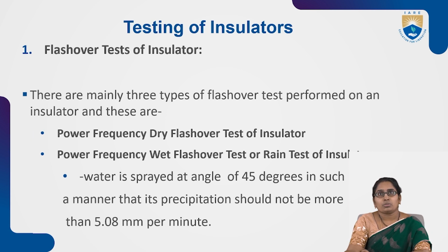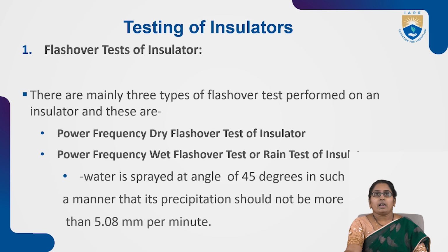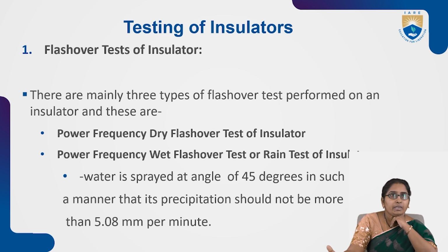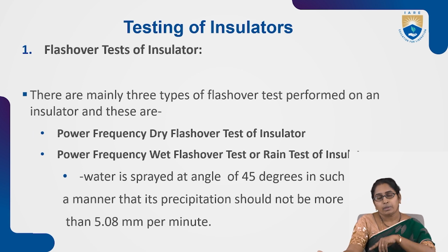At the same time they will apply the voltage at operating frequency 50 hertz under this condition, and they will see at which value of voltage there will be a flashover.